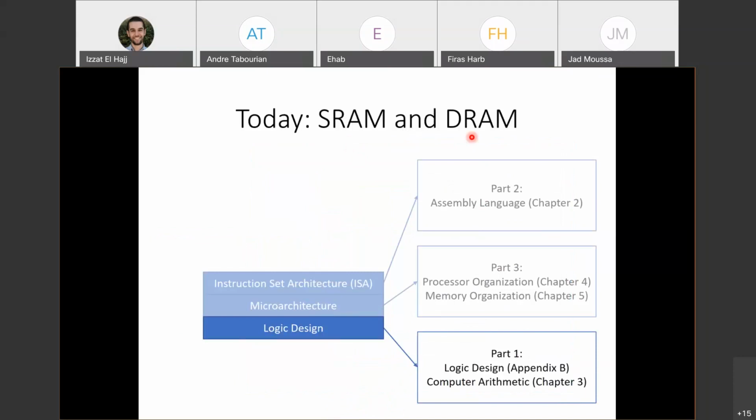I have a quick question. The D flip-flops we learned about, are they meant to be used specifically when the active edge is the falling edge, or can they be used also when the active edge is the rising edge on the clock? Okay, so the specific D flip-flops that I showed, the active edge for those is the falling edge. But if you just switch where you put the inverter, you can get a D flip-flop where the active edge is the rising edge. Okay, thank you. You're welcome.